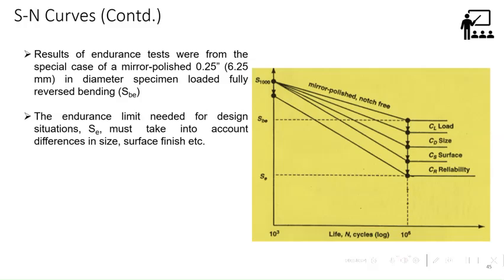In the stress life approach, as you were showing a couple of slides before, we have a mean stress, right? And in the SN curve, should any mean stress correction factor be applied for fully reversed loading or non-zero mean stresses? For fully reversed, the mean stress is 0.